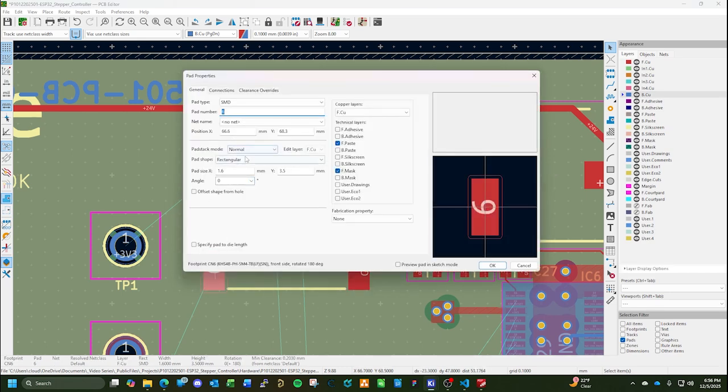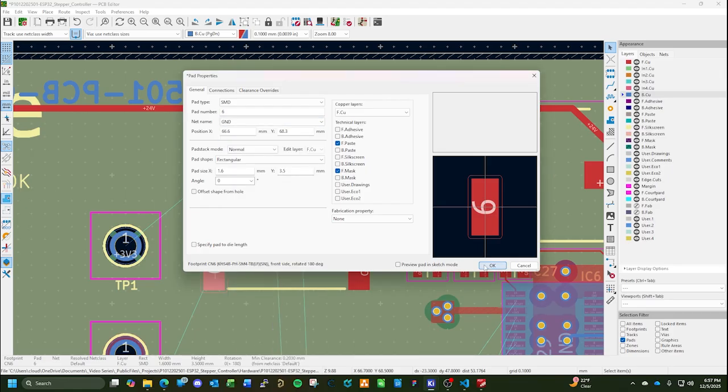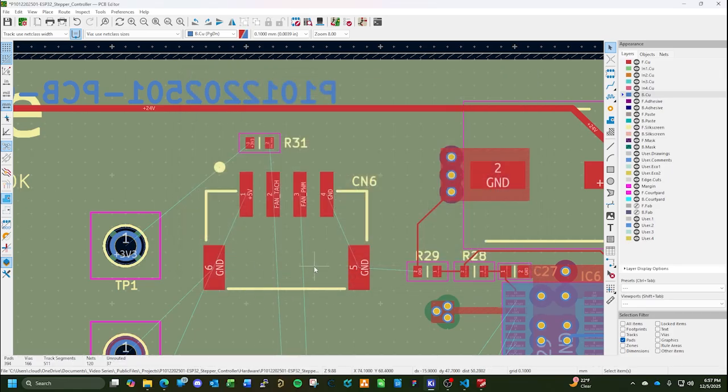Something's telling me, mainly because I want to give this connector a really nice ground port, something to hold on to when it's soldered. Because remember, you're going to be bringing the connector in from this angle to plug it in, and you're only going to have these two little tiny pads to hold back that kind of force.